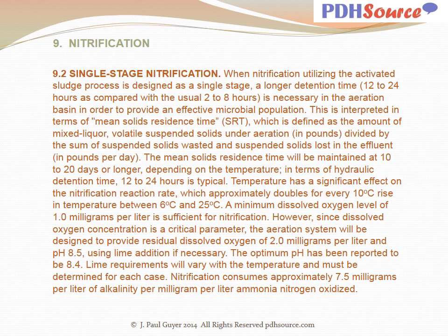Temperature has a significant effect on the nitrification reaction rate, which approximately doubles for every 10 degrees centigrade rise in temperature between 6 degrees centigrade and 25 degrees centigrade. A minimum dissolved oxygen level of 1.0 milligrams per liter is sufficient for nitrification. However, since dissolved oxygen concentration is a critical parameter, the aeration system will be designed to provide residual dissolved oxygen of 2.0 milligrams per liter and pH 8.5 using lime addition if necessary.